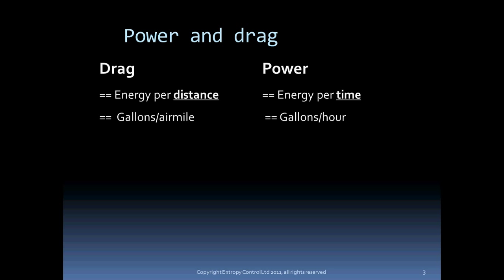When you're gliding, you're converting height energy to distance. It's no different when you're converting chemical energy in the form of gasoline into distance. The physics are the same, so the best glide speed also gives you the most air miles per gallon. I should mention that the speeds may not be completely identical because a gliding aircraft has additional drag due to the windmilling propeller.